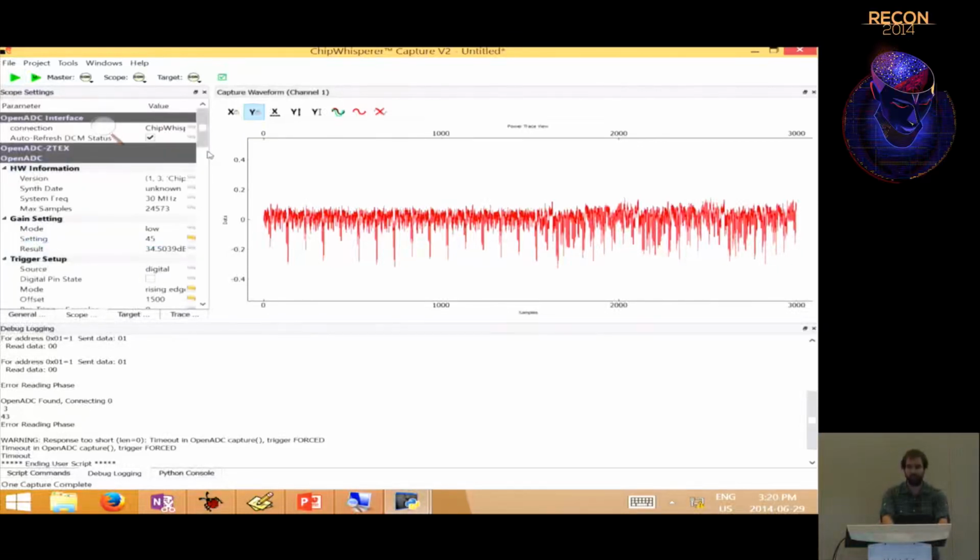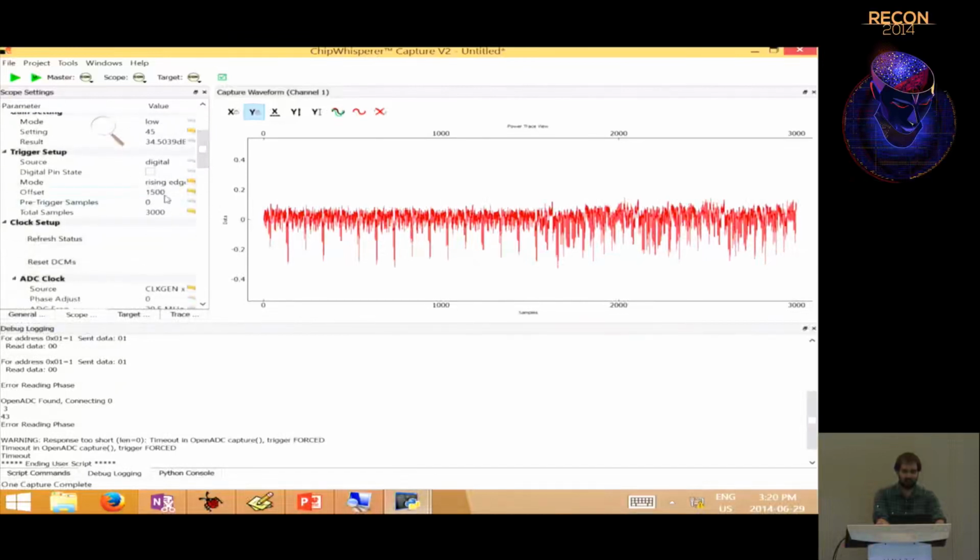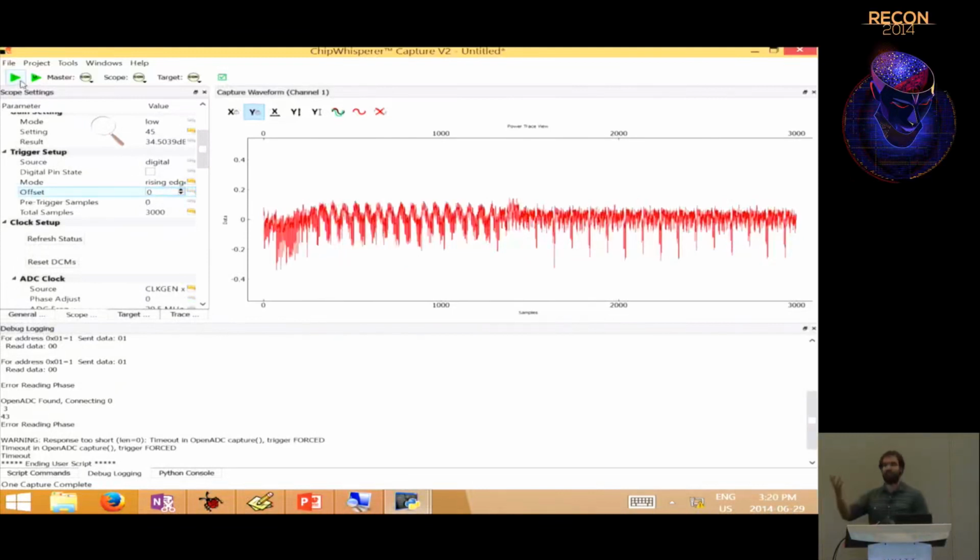And one of the other questions: right now, you need some way to synchronize approximately to where the encryption is happening. So right now I'm using an I/O line that goes high for determining the encryption is happening. In real life, of course, you can just say, well, I sent it the data at some point, and between sending the data and getting the response, it's done the encryption.